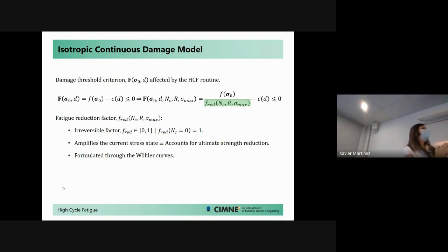And there are basically two alternatives that you can use when you want to quantify it. Well, you can apply it inside this first term over here. So we are dividing the stresses by this function. And what we are actually doing, since the function moves between 0 and 1, starting at 1 and downgrading until 0, is we are incrementing the stress state inside our material, okay? And we are amplifying the stresses according to this reduction coefficient until we reach the strength threshold and we begin to have nonlinear effects inside our material.